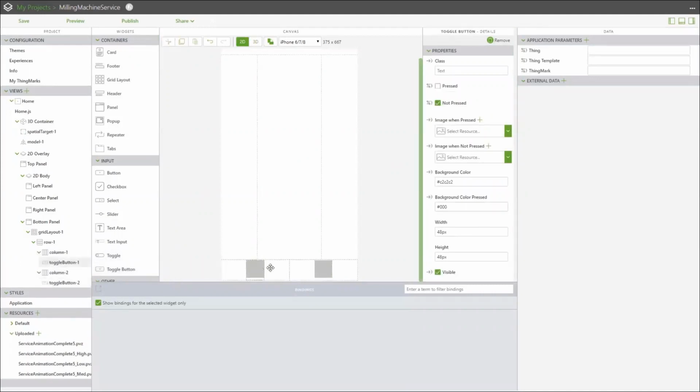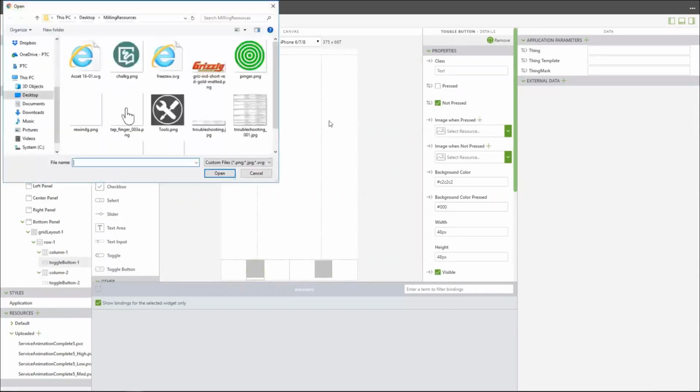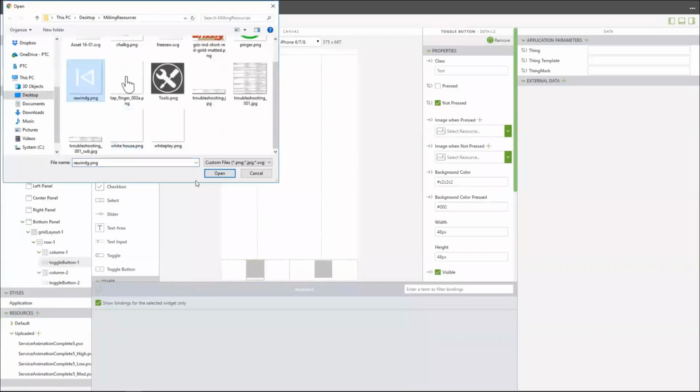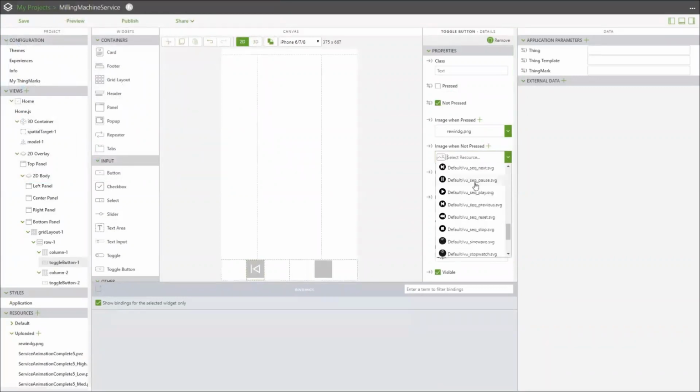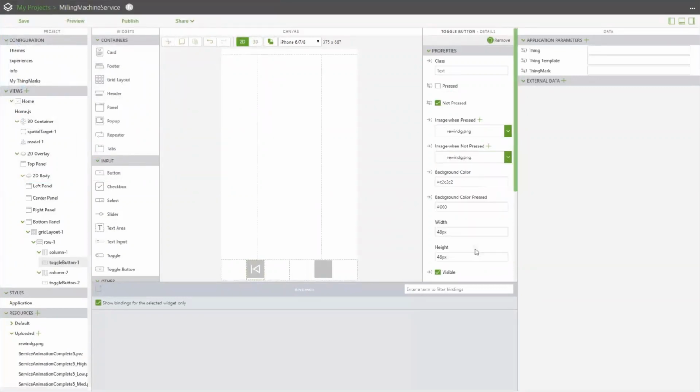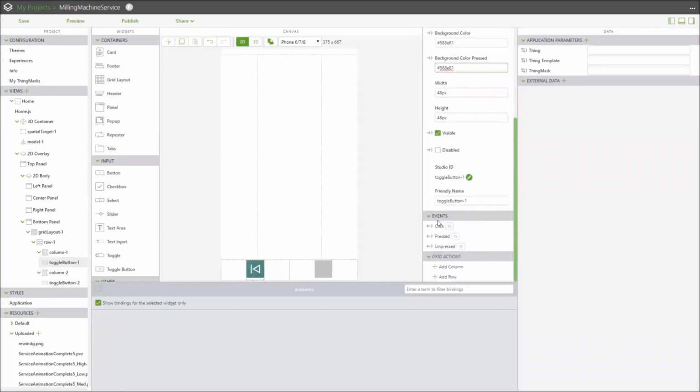So we're going to bring in two specific toggle buttons. And we can also define if we want to use a PNG image that we have stored on our computer locally as our image, or we can just go with a stock image that we have within Vuforia Studio itself. So essentially any PNG image can be used as a button or pretty much anything else within Vuforia Studio. And also in Studio, we have like a full CSS editor. So if you want to, I'll say make the Studio experience match your company style guide, so long as you have the CSS code, you have that capacity.